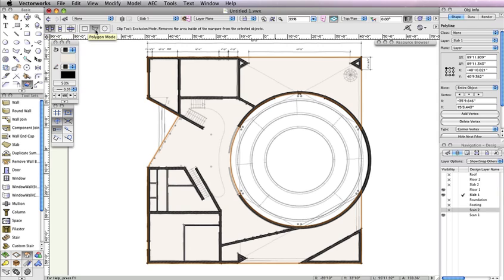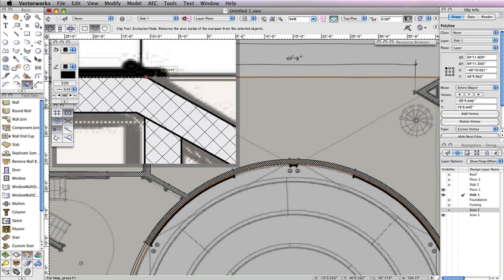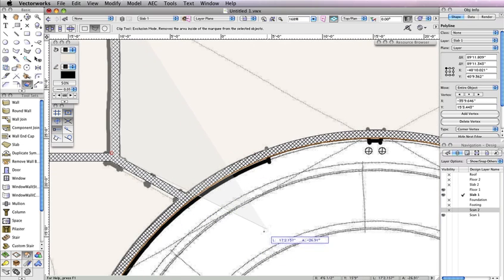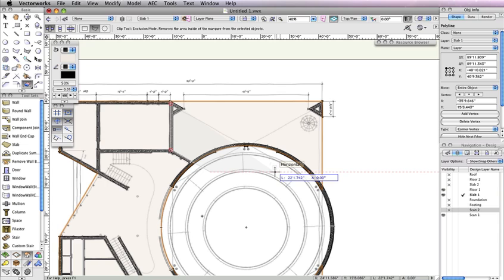There are only 3 vertex points along the inside face of the walls that need to be exact for the clipping boundary you are creating. Please click on these points in the same order as shown. Then, for the remainder of this polygon, simply set the points as close to the same area in your own drawing as possible. The last click to create the clipping boundary will be the same as the starting point. Once the last point is set, the polygon will be clipped according to the shape you just drew.